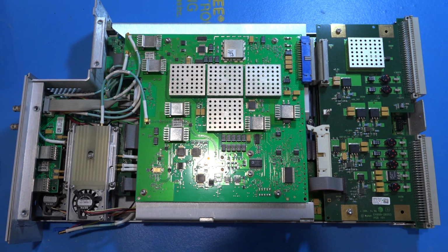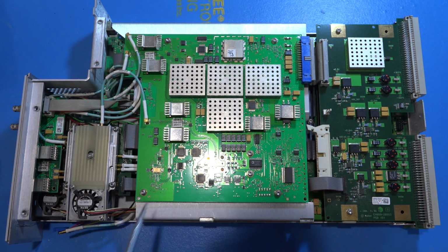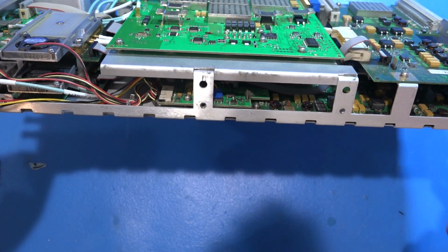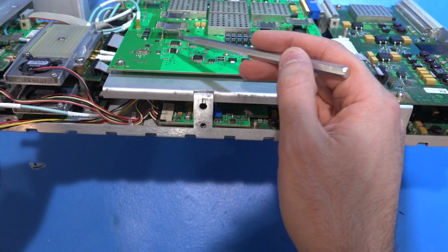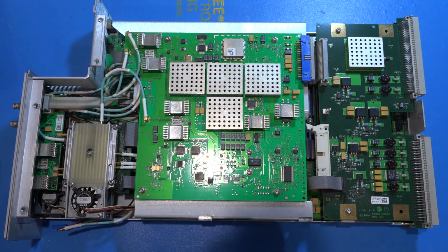I'll tell you what my strategy is, and this thing is full of custom ASICs and custom modules from Keysight. Of course, you can see many amplifier modules here in various locations. Interesting thermal design on those heat sinks, which are designed to interface to the PCB. There is nothing connected to them. The PCB itself conducts heat laterally and then onto the heatsink and out, which is a clever little design. I've seen it in other places as well.